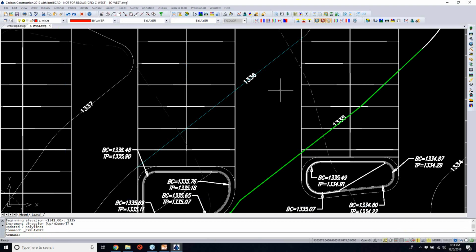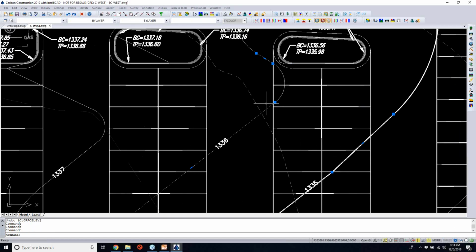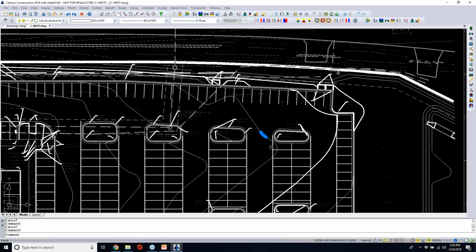So you can sort of see how those things are. Now, in this case, I haven't actually gone through, and I would probably need to do a join nearest. So let's make some quick changes in here. I'll go ahead and undo that, because that was one of the things that was sort of vexing about the way these contours were provided to us. As it turns out, the design contours in here did not carry through many locations in terms of their overall length. So these were all segmented, even though they look continuous, they weren't.